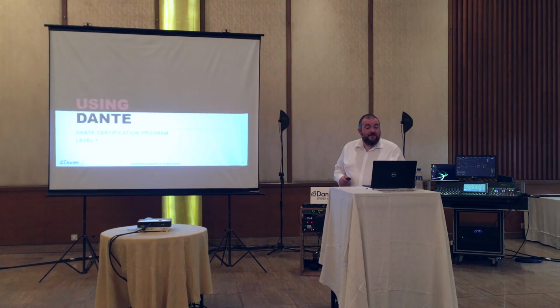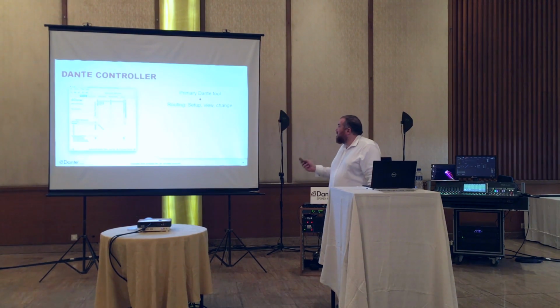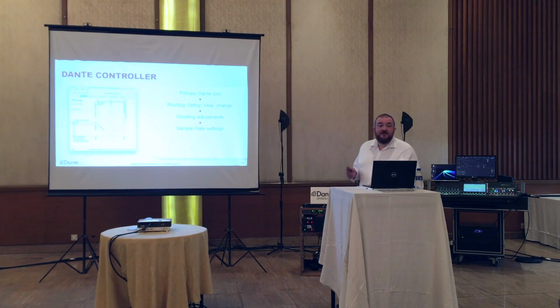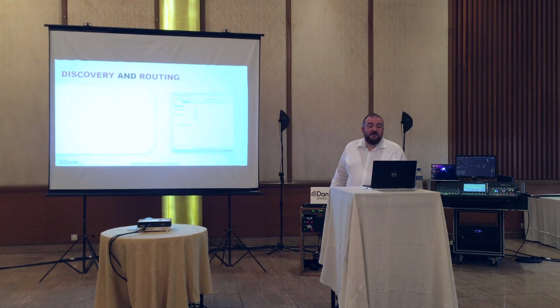So a few things on using Dante. We have our Dante Controller software package, which is our primary Dante routing, setup, viewing, and changing tool. We can make clock adjustments. We can change the sample rate settings of devices. We can change the latency settings of devices as well. And it also gives us clock and latency monitoring, so we can see how healthy devices are in the network.